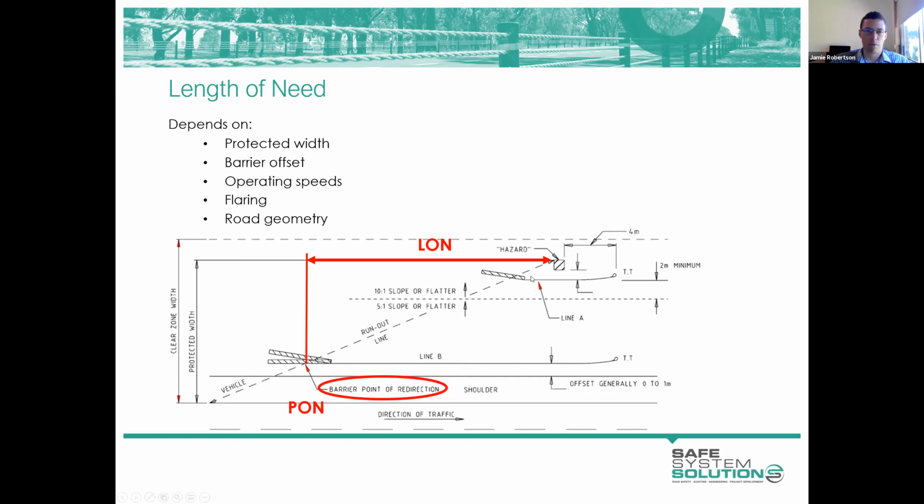We would end up with a quite wide area of roadside and the potential for rollover within that area potentially. So it's not a treatment that's preferred as a general rule. We're locating our barrier closer to the edge of the road, but looking to provide enough space for a vehicle to pull over in an emergency situation.